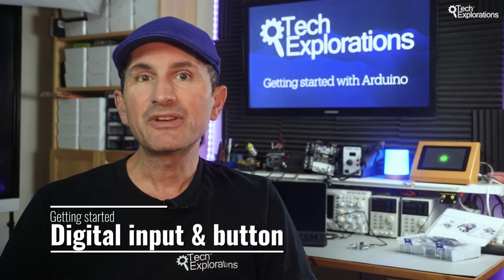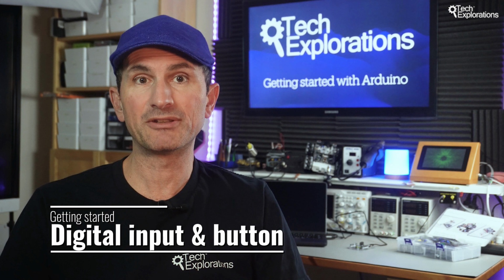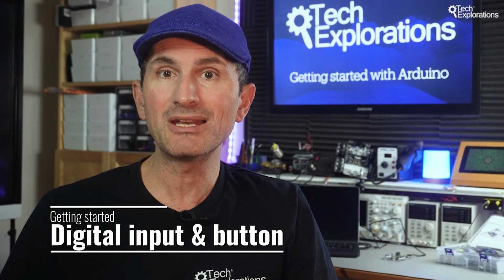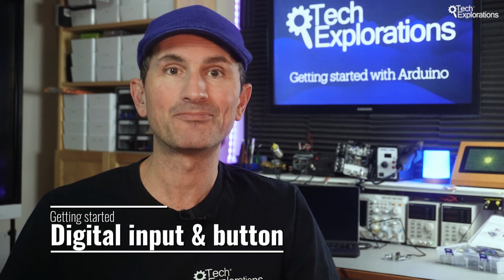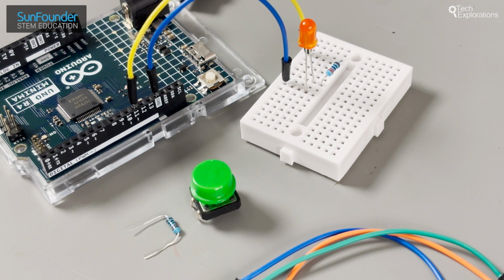Welcome back. This video adds a new interactive element to our Arduino project, a push button. You learn how to read the state of a button using a digital input pin and use it to control an LED. Let's start. You'll need a push button, the LED and resistor setup from our previous tutorial on pin 11, a couple of jumper wires and a 10 kilo ohm resistor.